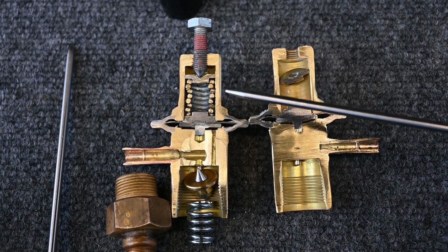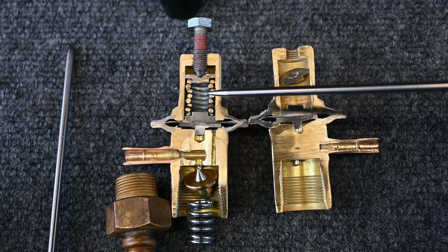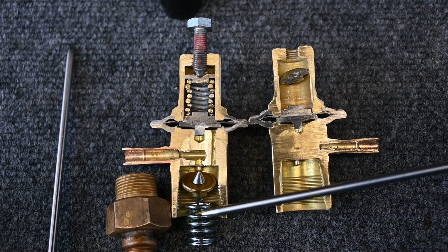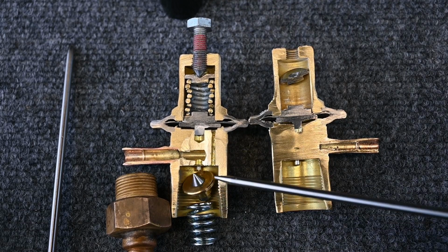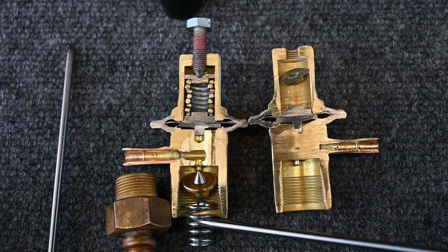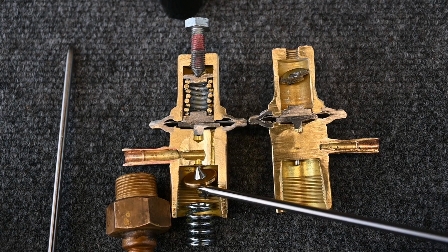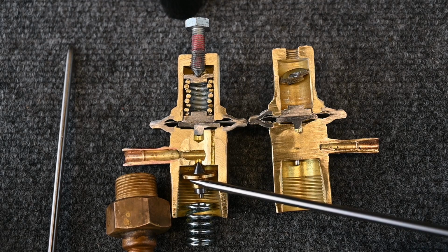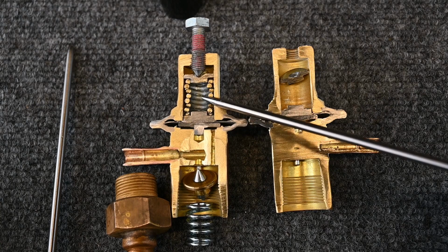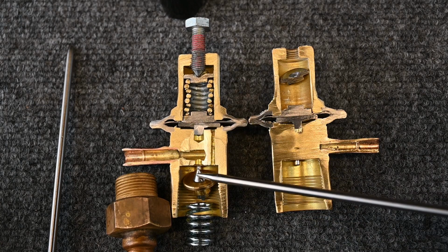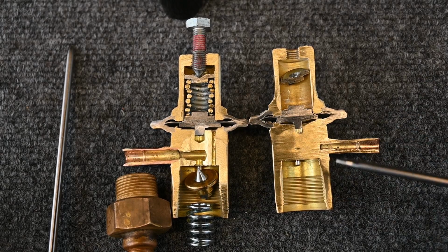So if I set this for 120 psi, anything less than 120 psi, this spring will take over and will push this open, overcoming the spring pressure. Anything above 120 psi, the pressure pushes up on this tube, works with this pressure, and it pushes this up. When this gets pushed up, the spring pushes this closed. And as the pressure starts to drop down, then it allows less pressure here. This spring overcomes this spring, and now it pushes this valve back open. So it's opening and closing, opening and closing, opening and closing. Pretty cool how this works.